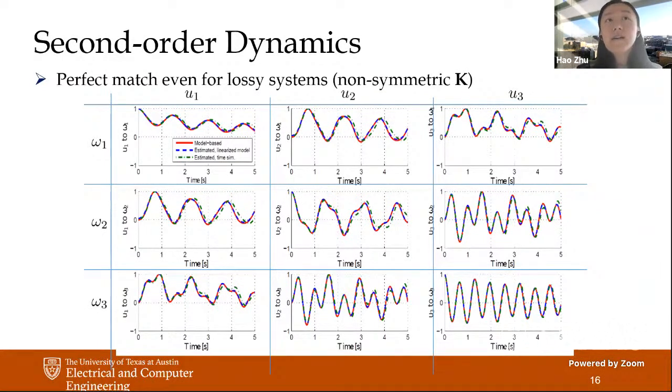So if there is a disturbance or outage in generator 1, then the first response will be coming from the generator itself. Its frequency will drop immediately. So that's why the frequency response starts from the highest value and then oscillates to smaller values. And if the disturbance is happening in generator 1, then the other generators will slowly notice that there is an imbalance, and then they would slowly respond to that imbalance by increasing from a zero deviation to the peak value. So overall, all these frequency responses look like oscillation, as you saw earlier in the animation.